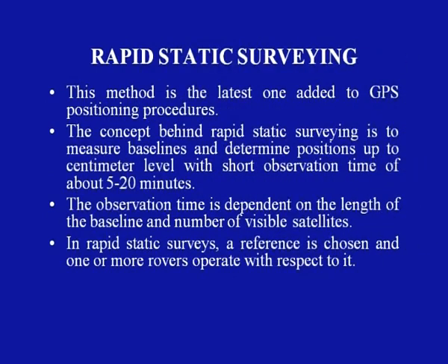The next is the rapid static surveying. This method is the latest one added to GPS positioning procedures. The concept behind rapid static surveying is to measure baselines and determine positions up to centimeter level with short observation time of about 5 to 20 minutes.